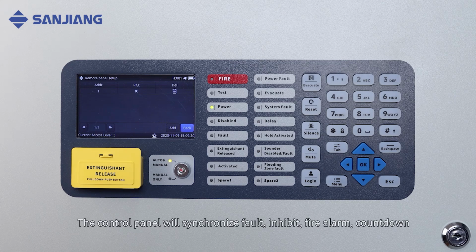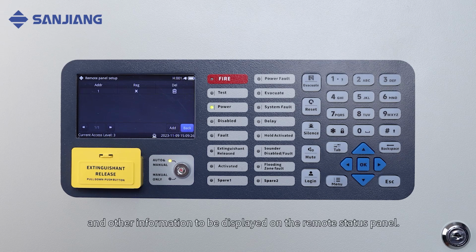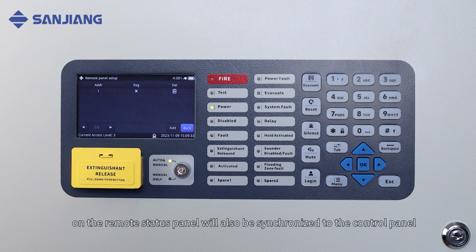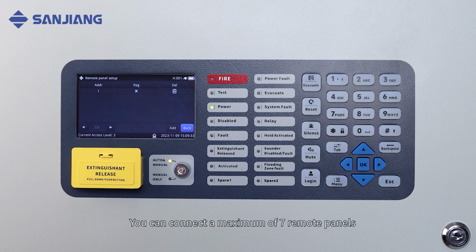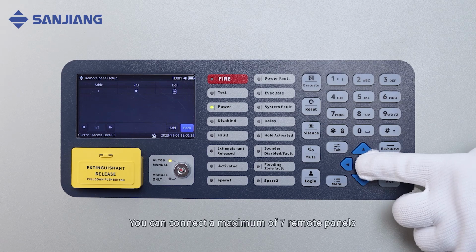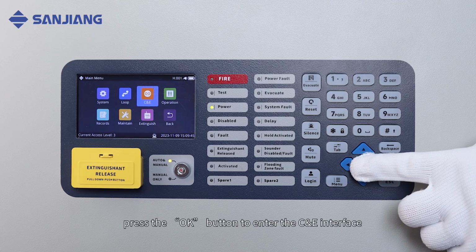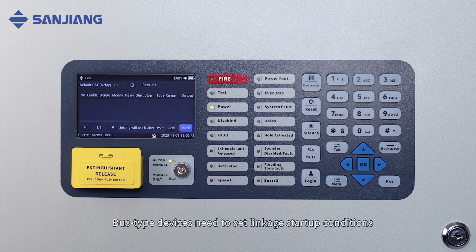The control panel will synchronize fault, inhibit, fire alarm, countdown, and other information to be displayed on the remote status panel. At the same time, some information and operations on the remote status panel will also be synchronized to the control panel. You can connect a maximum of 7 remote panels. Select CNE, press the OK button to enter the CNE interface. Bus-type devices need to set linkage startup conditions. You can choose to set system linkage and zone linkage to achieve the purpose of starting fire equipment.